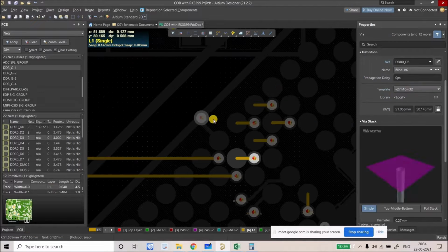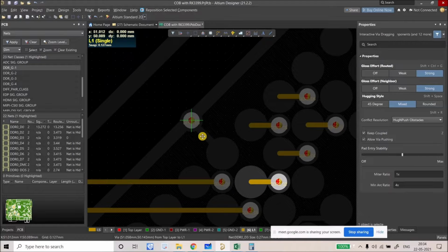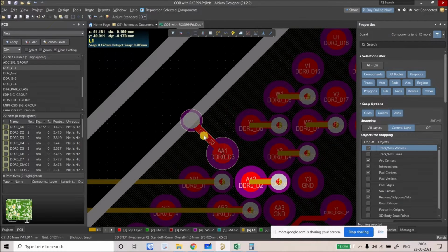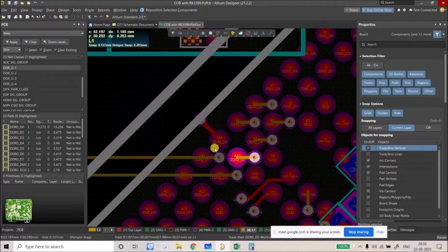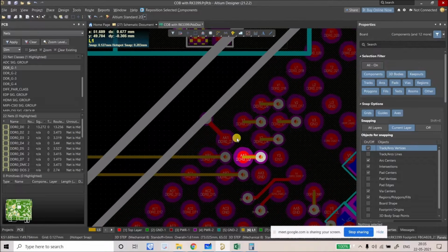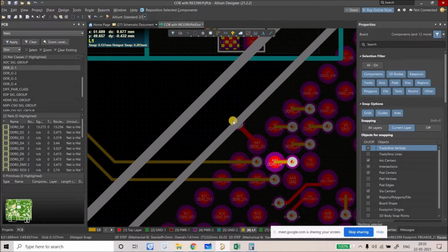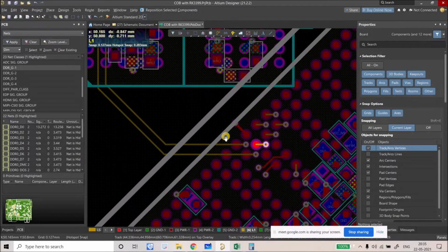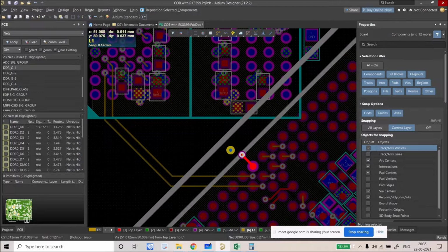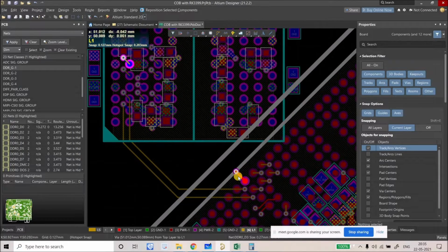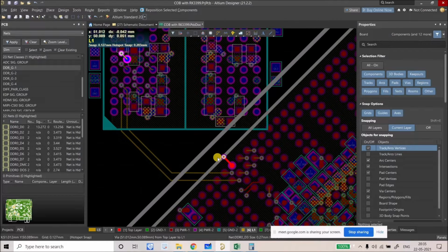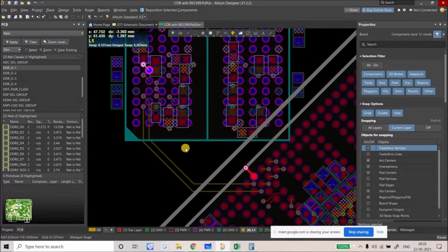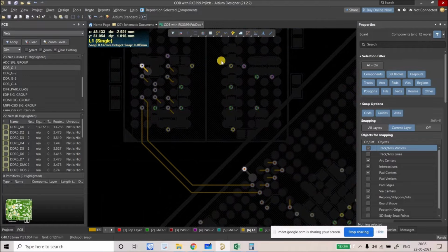I'm just going to remove it as of now. So here you can see I just routed that on the top layer and a little bit outside of the SOC because this is at this side, right? So it is okay to route it a little bit outside because we have a lot of space here. Let's see if in future we face an issue because of this, then we will adjust it here and there somewhere. Okay, so again go back to single layer mode.